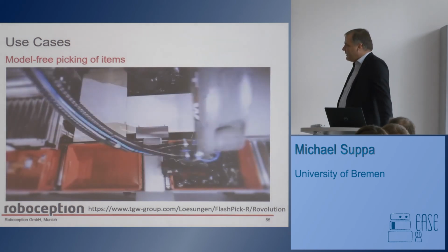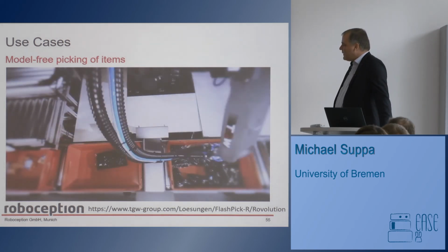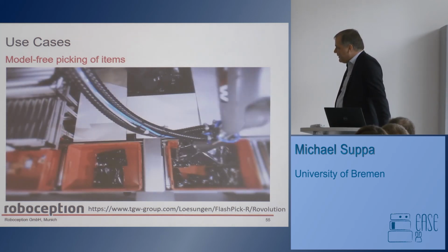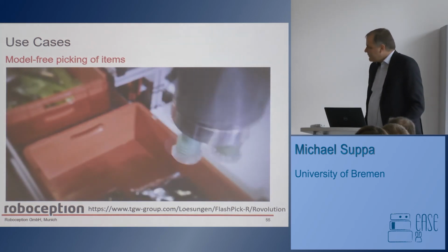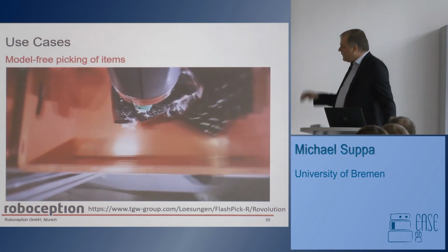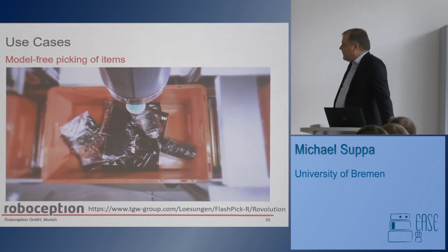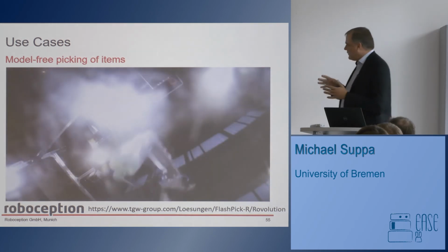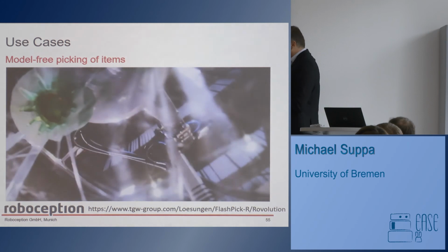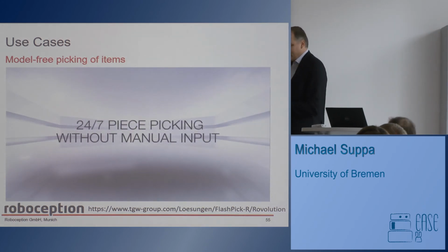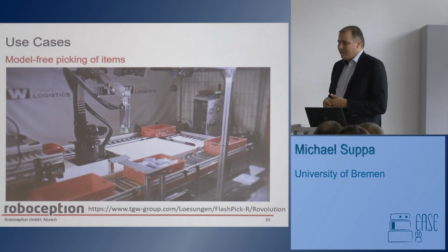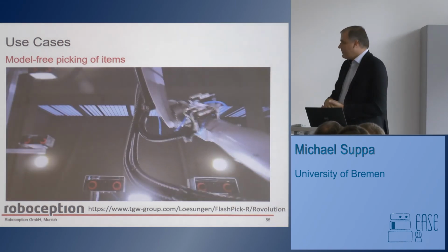But it just helps to make it sure. And what we can do with the camera is basically capture these sports goods. They are all in these plastic foils. You can imagine that it's bad for vision, but still the only task we have to do is basically to find some position on these objects. So you don't care what kind of object this is. If you put another object in, it doesn't matter. It's always going for a suction surface.